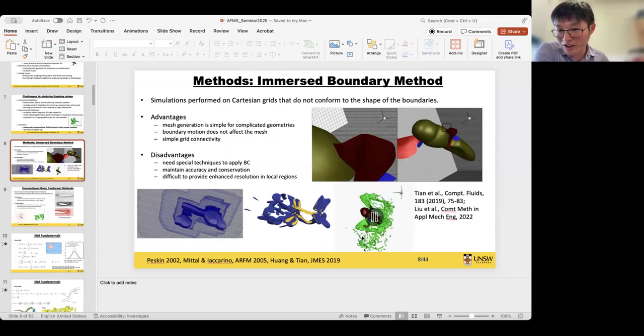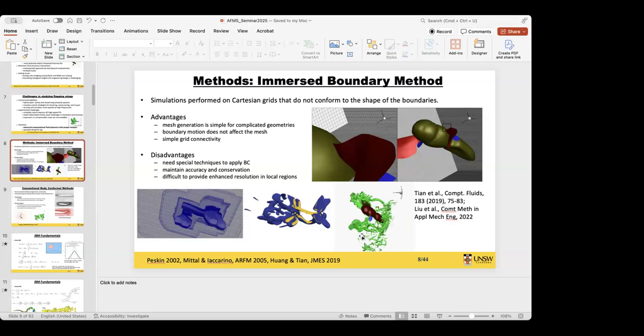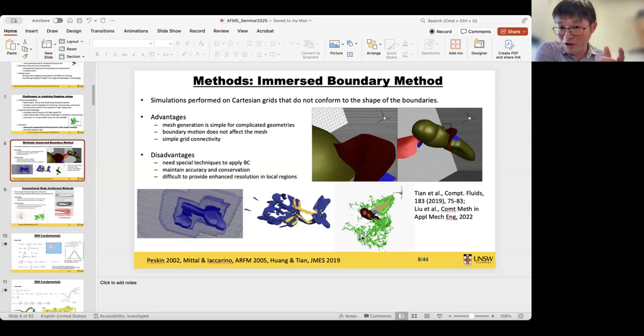If you look at the velocity of the body and the wing, the velocity of the body is much smaller compared to the wing. So it is negligible. But this is a new field again, because sometimes the interaction between the body and the wing can affect the leading edge vortex structures, and this can affect the lift generation significantly. I think Professor Zhong Yang discussed this in his 2009 paper for locust.